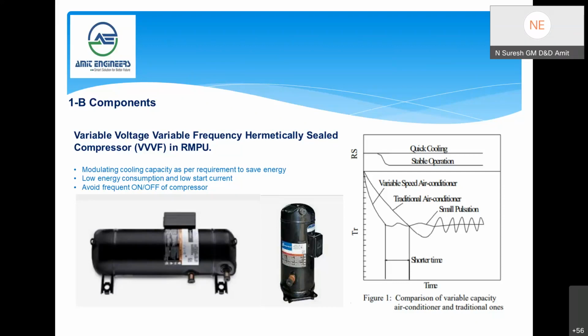At that time, more cooling power is required, so both compressors will work. Once the cooling reaches the set point, one compressor will be off. The other compressor will work based on the PID control, that is, the set temperature versus the return air temperature.